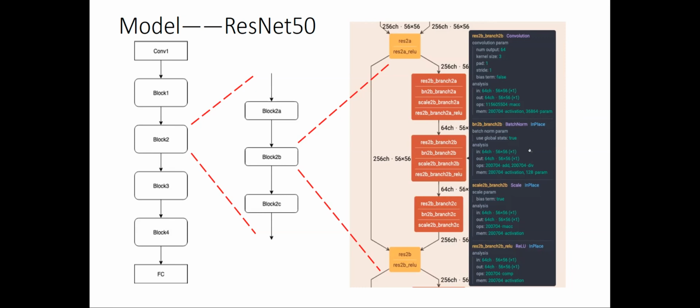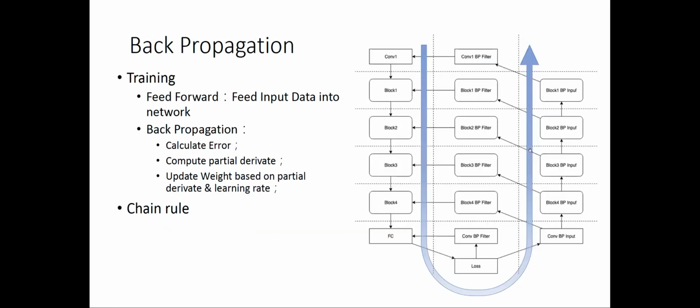But the downside is that it does not sustain the computation throughput. So that does not meet the highest performance requirement as we require when, for example, we want to beat the MLPerf performance when comparing to another device. So we need some of this customization, or let's say high-performance convolution kernels for different shapes of convolution. That's very important, and that's the key to achieve very high performance throughput in this AI ASIC.